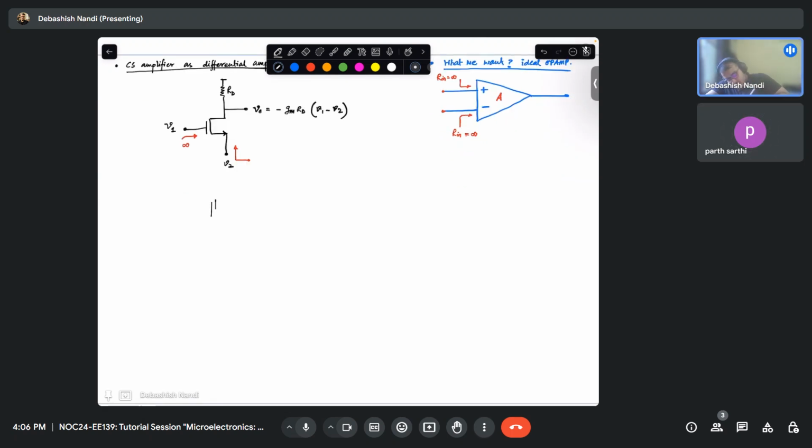So what is that? How do you calculate that? You put this grounded, you put a V test here, and you have your RD here. So this is your I test. What is this current? This current will be gm times V test. If you ignore your r out, then what is V test by I test?